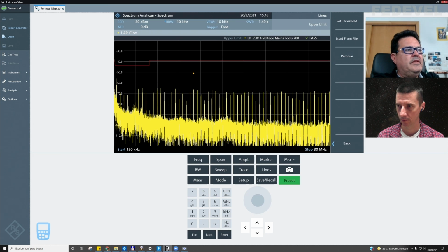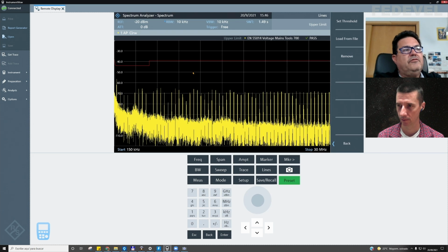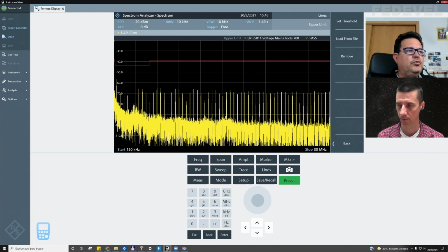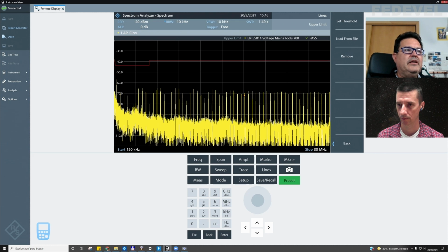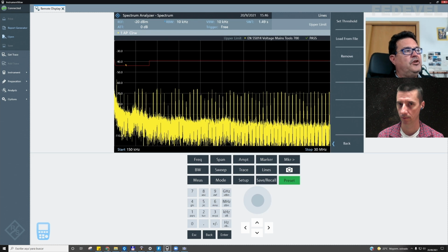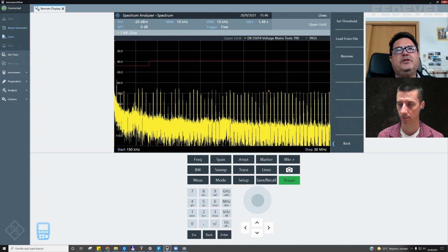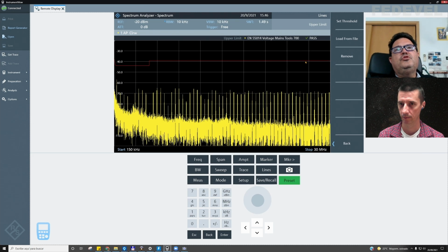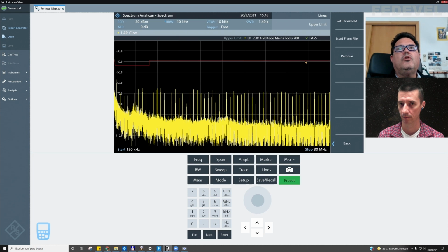Basically, this is enough to understand the problem. You need to understand that what we are doing is sending the signal we are injecting in the power supply to the spectrum analyzer or to the EMI receiver. We configure the spectrum analyzer following the regulation criteria, and we can plot some kind of limit to see if we are below or over the limits.